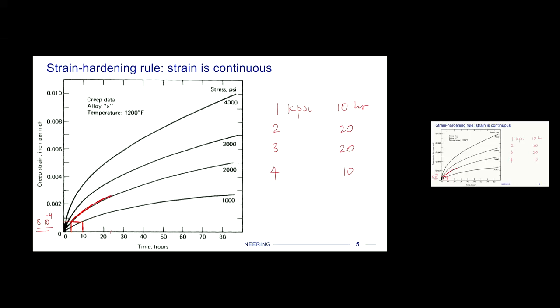Okay, and then I'm going to look at the incremental creep strain from that segment. And I'm not actually going to quantify it because you'll see now that we're just going to keep adding up on our creep strains, unless they overlap or something like that. But we don't drop back to 1,000, so we're okay.